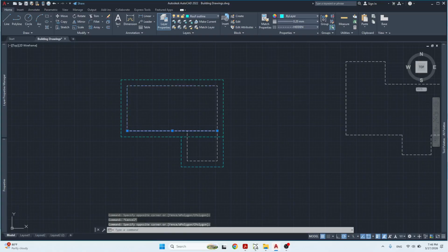Okay, so we're just going to draw our rafters. Make sure they are coming in at a 45-degree angle. So I have my thing set to 45 here. I'm coming in at 45 degrees, just going to draw them along, and then I could always trim them off after. That guideline is helping me there.